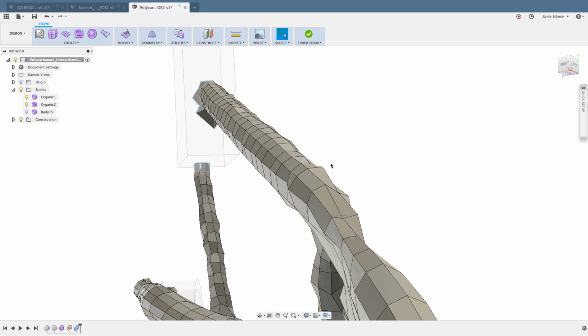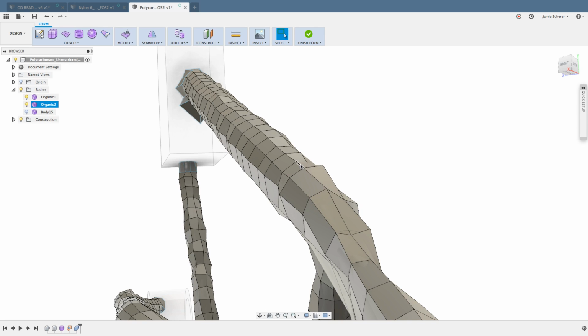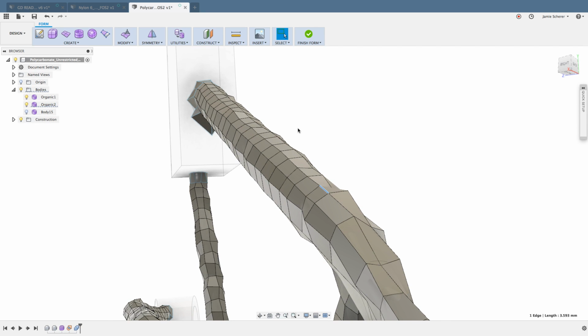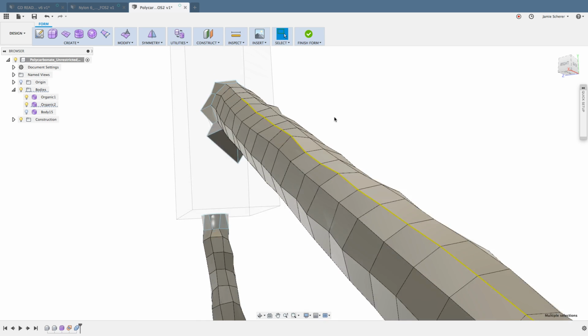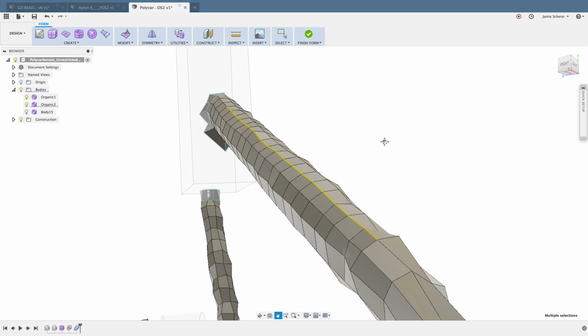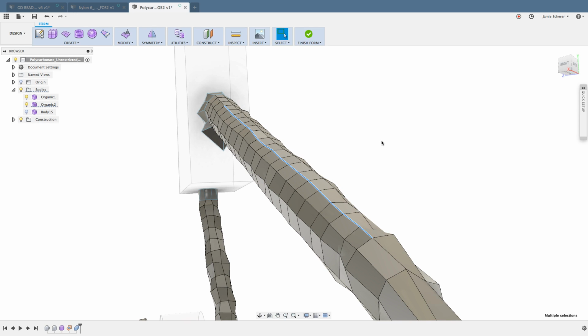New, a couple releases ago, is the ability to select an edge, hold Shift, and double-click another edge, which will select all of the edges between point A and point B. So this is another awesome way to not have to spend a painstaking amount of time selecting every one of those edges, but just saying, from here to there, I want every one of the edges in between.